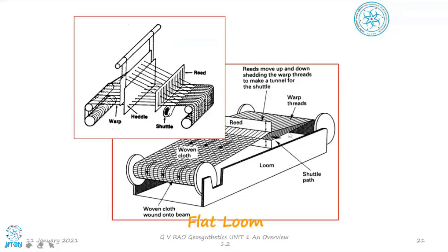And you see it is in two layers now. It is not simply wound like that. It's got two layers now. The two layers of these yarns are separated by what we call the reed. That means if the reed is going up, let us say this top layer is going to go up. If the reed is going to be moving down, naturally the top layer is going to go up. So the up and down movement of these yarns is helped by the reed actually.